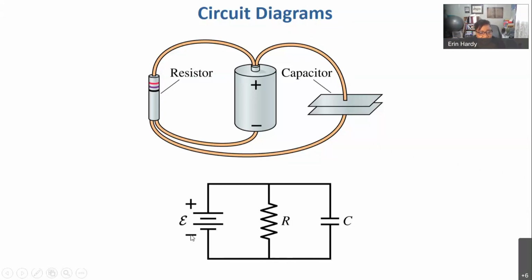I don't recall whether I mentioned it the first time that we saw a battery symbol in a circuit diagram, but a single cell battery has a symbol that looks pretty similar to what we saw for the parallel plate capacitor, only the lines that we use to indicate the battery do not have the same length. And if you have multiple sets of parallel lines as opposed to just one, we can interpret this as a multi-cell battery, where in all cases, the shorter of the two lines that makes up the battery symbol represents the negative terminal of our battery, and the longer of those two lines represents the positive terminal.